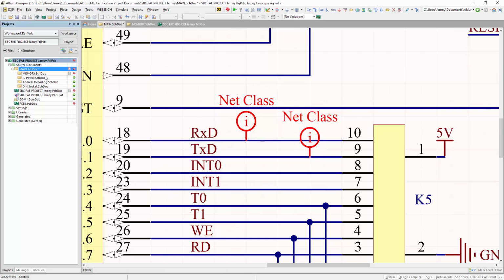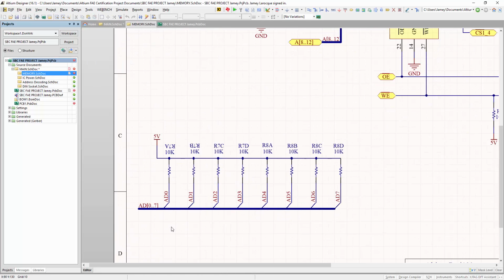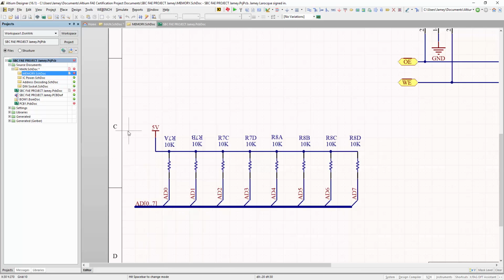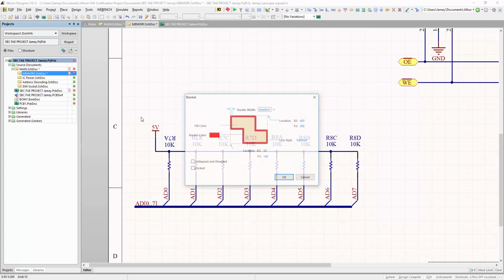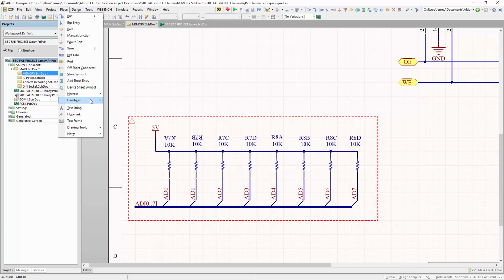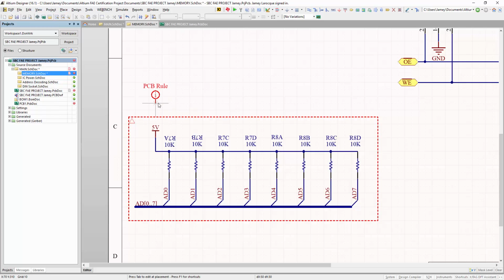The blanket directive is a powerful feature in Altium Designer's schematic editing domain. It can quickly be applied to a group of nets simply by covering those nets with a blanket. When placing a blanket, you can either define a simple rectangular shape or a polygon shape. This gives more precise control over coverage of the required net objects on a sheet.